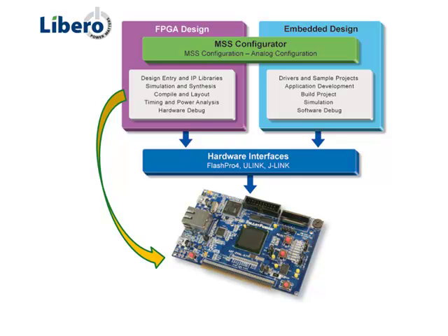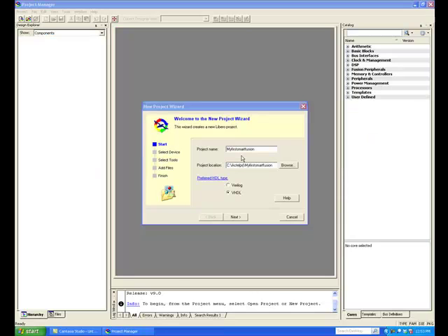Before starting your SmartFusion hardware design in Libero IDE, you should predetermine the IP cores that you will need for the design project and make sure they are downloaded from the Actel web repository into your local PC IP vault, typically located in the Actel Common folder on your C drive. For this project, the local IP folder already has the SmartFusion microcontroller MSS, CoreAPB3 bus interface, CoreAPB SRAM, and CoreUARTapb downloaded and available in the Common folder on the C drive.